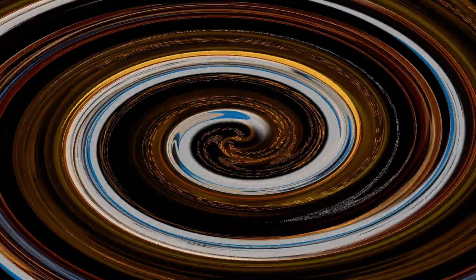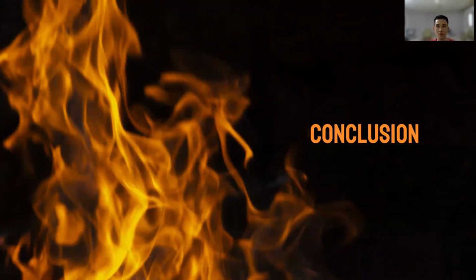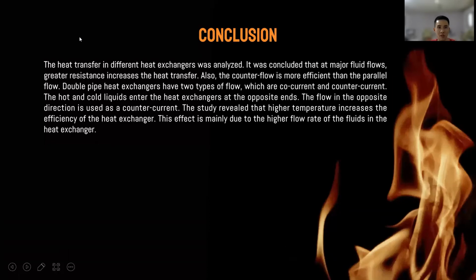Thank you. My matrix number is MA20067. I'll present the conclusion of the lab. For the conclusion, the heat transfer in different heat exchangers was analyzed. It was concluded that at the measured flows, the greater resistance increased the heat transfer. And also, counterflow is more efficient than parallel flow.